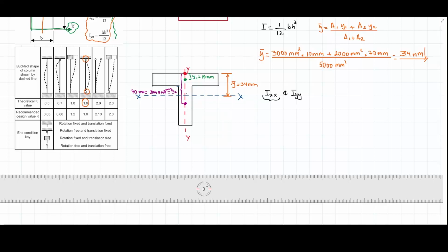So the moment of inertia of this combined section around this X-axis. To do that, as I mentioned, we need to take care of the fact that the inertia formula here is presented with respect to the centroidal axis, which we now have for each individual area, but the centroidal axis of these areas or sections is different from the centroidal axis of the whole combined section. So we need to do a manipulation to be able to find what's happening there. And what we need to include in our calculation is that the inertia with respect to any axis is going to be the inertia I know with respect to the centroidal axis, which happens to be this one here, plus something that takes into account that the centroidal axes of the sections themselves are not coincident with the centroidal axis of the combined section.